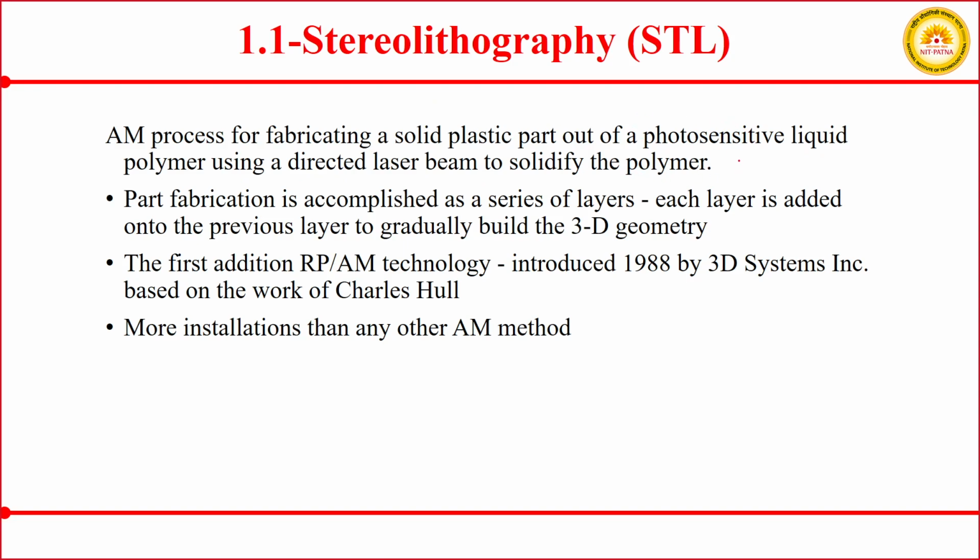So here what kind of liquid polymer are we having? It is a photosensitive liquid polymer. The kind of material that we are using is photosensitive. It means as soon as the laser strikes the surface of that particular liquid, it will get solidified. So using that principle, we print the desired component in the stereolithography technique,